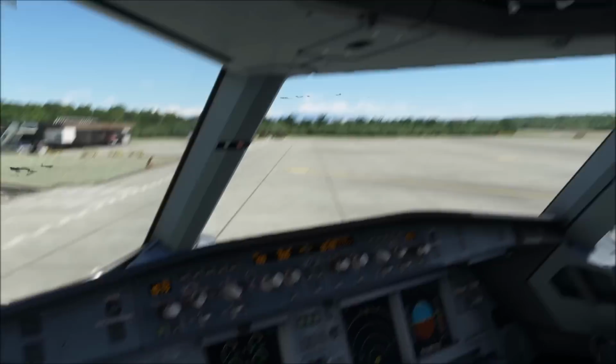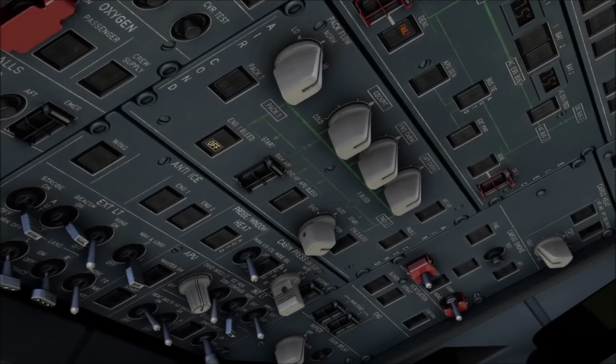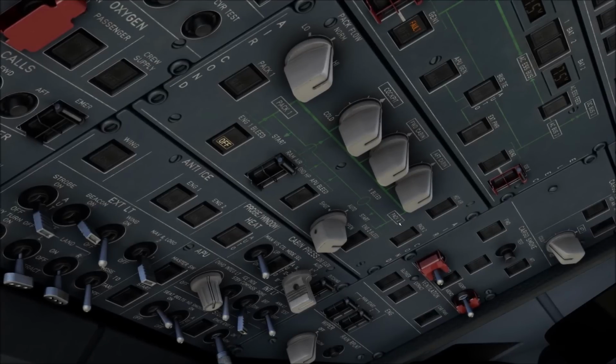Before the second engine start, APU bleed off. The bleed valve of the supplying engine reopens and the cross bleed valve closes. So, engine bleed on the supplying engine, that's engine number 2, turn on. Engine bleed on the receiving engine off. The receiving engine is going to be engine number 1, the one that we want to start, and that is off. The bleed valve of the receiving engine is closed to avoid reverse flow leakage. Okay, cross bleed open, and it is still open from our previous start procedure.